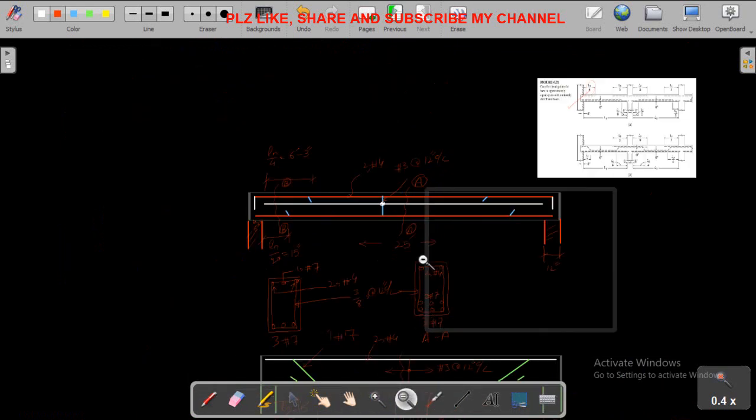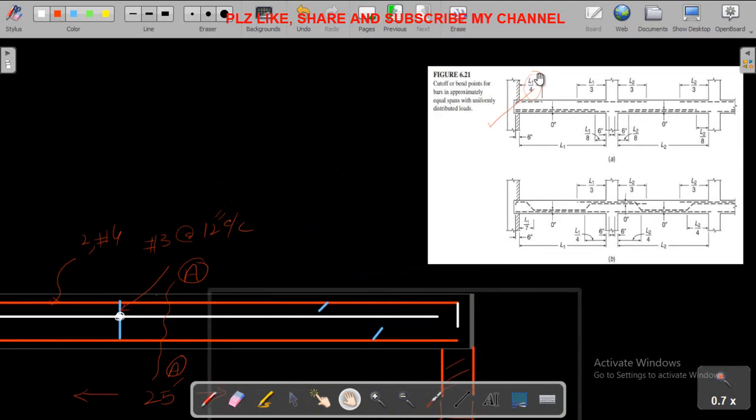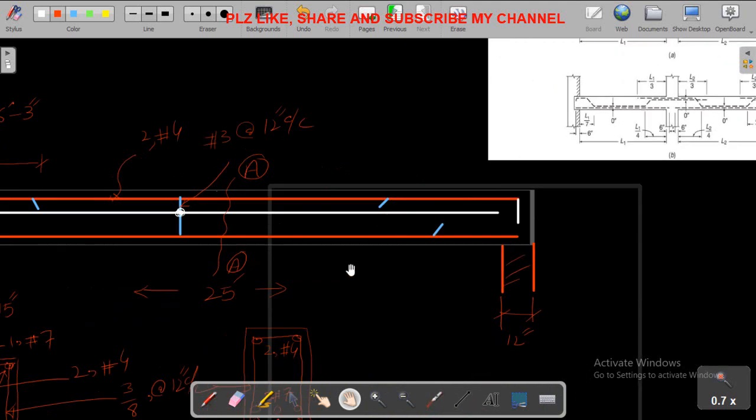That is how you can curtail your bars. And here you can see the detailing Ln/7, and the bars at the top should be cut off at a distance of Ln/4 from a discontinued edge. And this is all about the detailing.